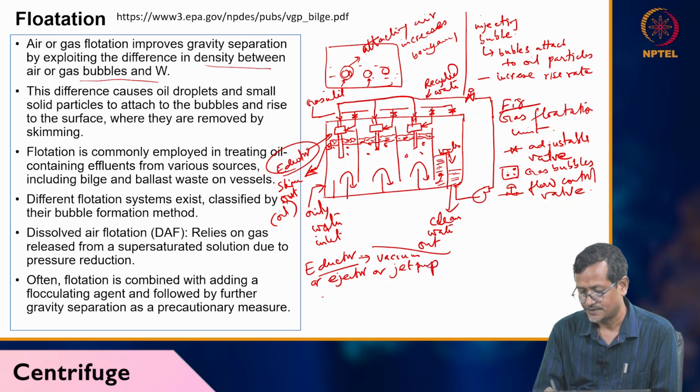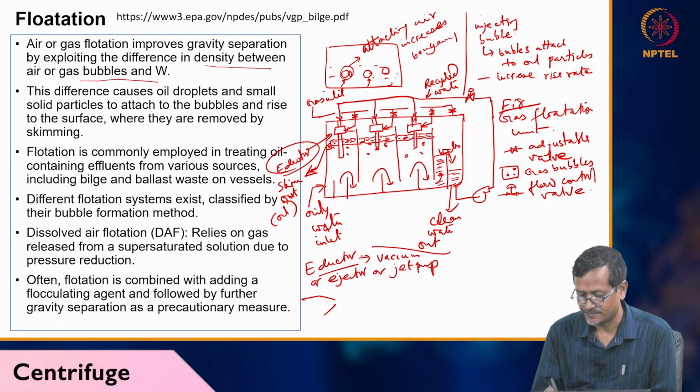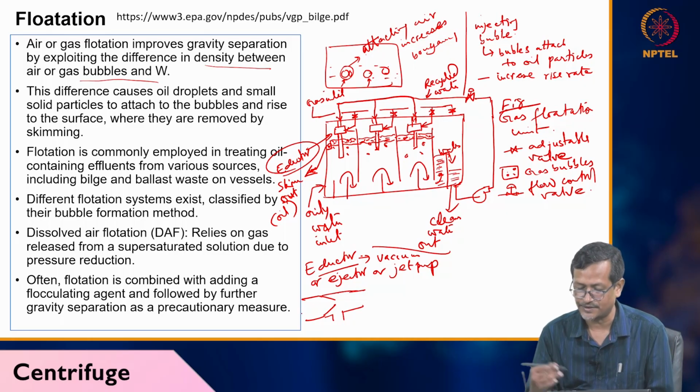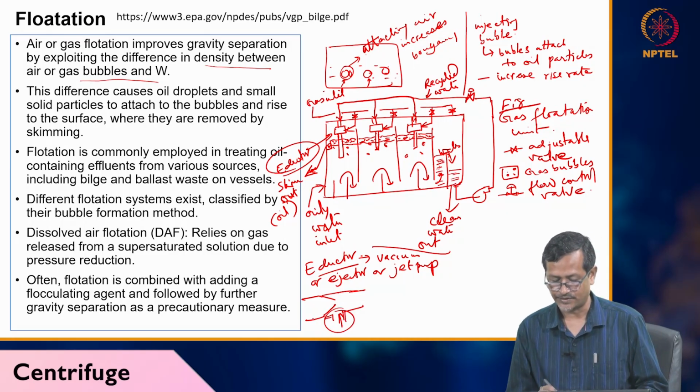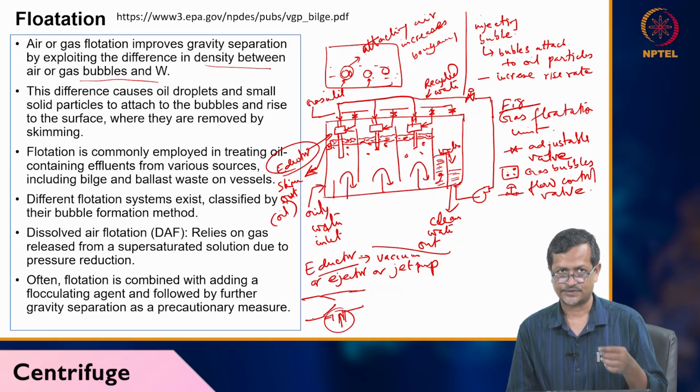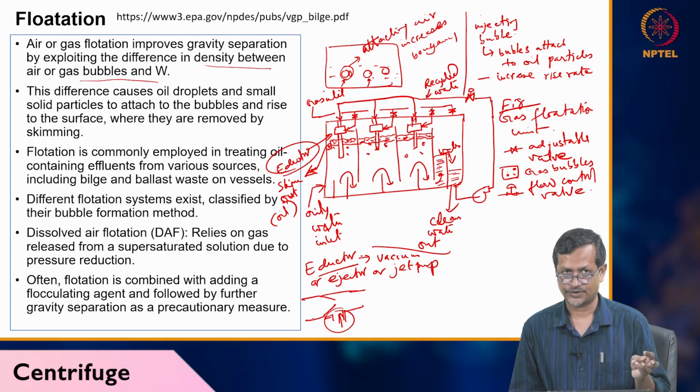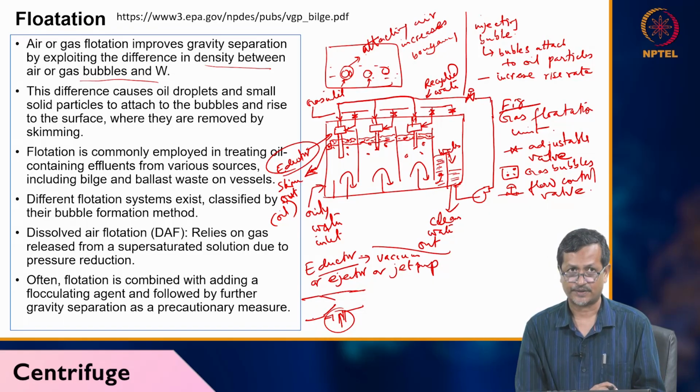I already explained, I think, that a jet pump has a small nozzle and it sucks in some other fluid. So this way the eductor, ejector, or jet pump works. When sucking some fluid, that means you are creating low pressure. For this, you can see your desalination lecture, where I explained how a jet pump creates vacuum for your MSF system.